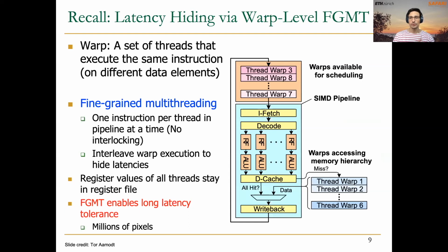Remember, even though this new architecture looks fascinating, we already know the basics of how it works. Remember that GPUs internally use warps, and they execute instructions for different warps in an interleaved manner, in a fine-grained multi-threaded manner.